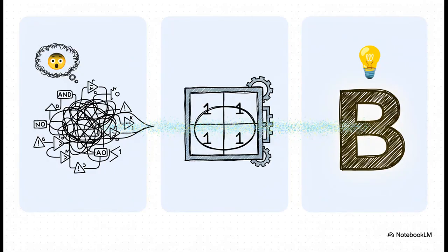So let's take that big, ugly expression from the very beginning. If we plot that one on a K-map and follow our rules, we find we can circle a big group of 4 ones, a quad. Now, if we look at what stays the same inside that entire group, we'll see that the variable a changes, so it's gone. The variable c also changes, so it gets eliminated too. The only thing that stays constant for that entire group is that b is always a 1. And so, that whole complicated mess of logic from the beginning simplifies down to just B. Seriously, from all that to a single letter.